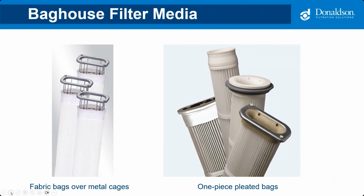Pleated bags have a couple really main advantages. One is what I just suggested, that it's significantly less time to change it out. And the second thing is you can replace a 12-foot regular bag and cage with a 5 or 6 foot pleated bag, and then end up with a little bit more filter area. So that lifts the bag up out of the airstream a little more. So if you have abrasive applications or otherwise just tough issues with your dust collector, a lot of times pleated bags can solve that for you.